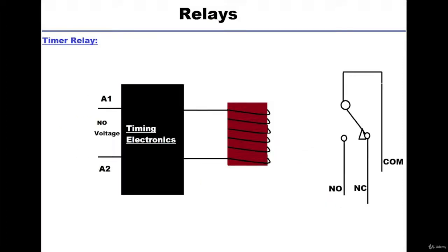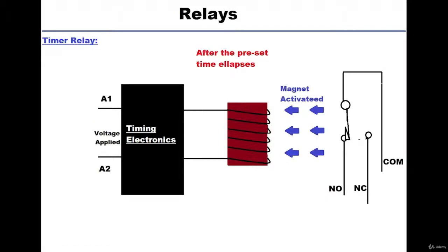Now, there is another type of these relays, which are the timer relays. Timer relays operate on this principle. You energize the coil, and after some time, the load will be connected. This amount of time is adjustable beforehand. The way it delays the output is using electronics which are designed within this relay. So we adjust the time that the relay is going to take until it latches the output. Then we energize the coil, and after this time has elapsed, the contact is going to latch.